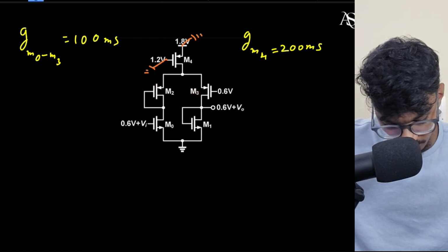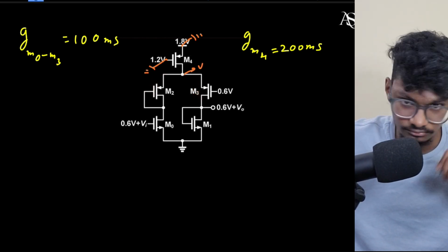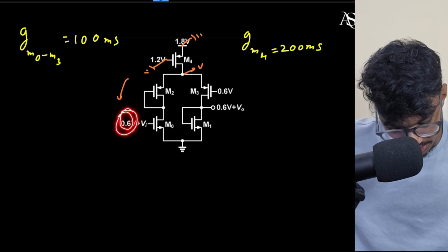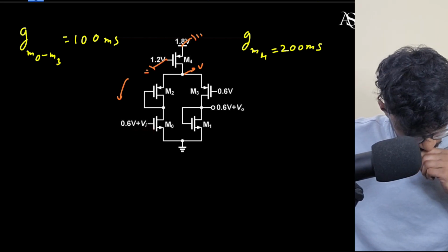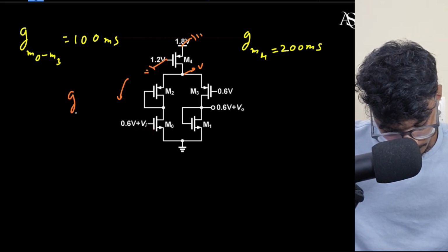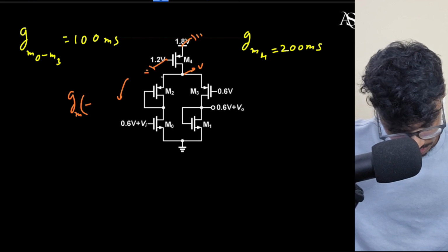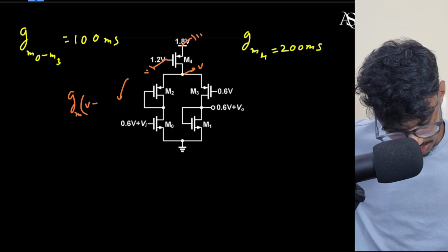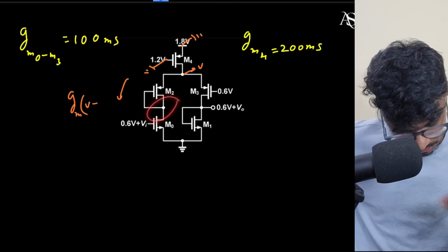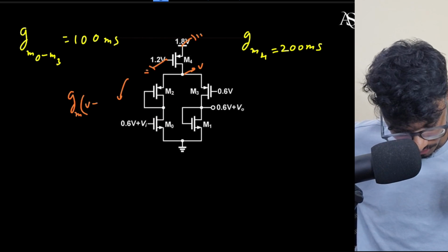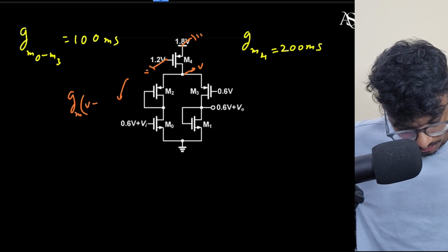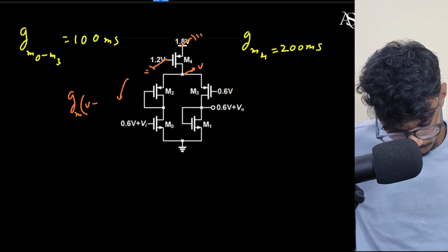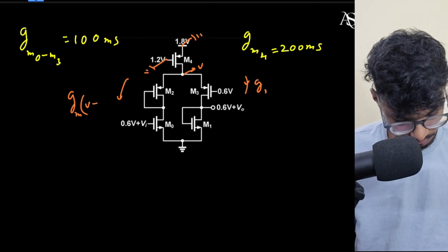So again, I will assume some potential here. I can assume some potential as V. So if I assume some potential V here, the current through this will be, right? This DC source will be 0. This will be VSG. So this current will be GM into, not minus, sorry, this is 0, sorry, V minus, I don't know this potential. Fine. Although this is grounded, right? So this is grounded, so the current through this will be what? The current through this will be GM times V, right?